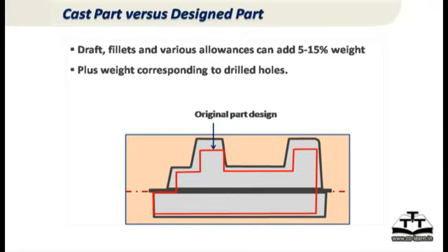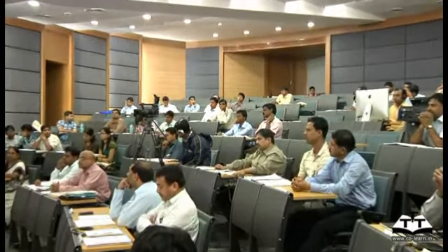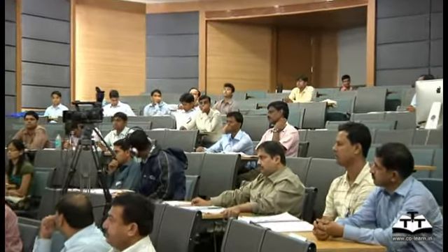So in most cases, the tool designer or pattern maker designer has to select a draft angle, which is a very critical part. Which factors does one designer have to consider in selecting a draft angle? Because many times the machining designer doesn't mention that draft angle, but the casting designer has to consider it, and many times tooling failure also happens because of that draft angle.